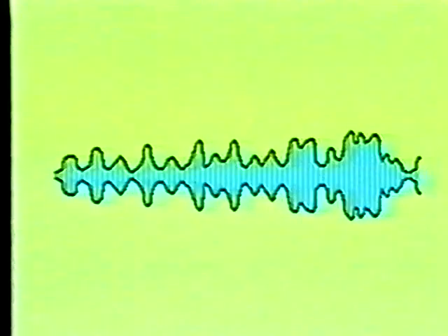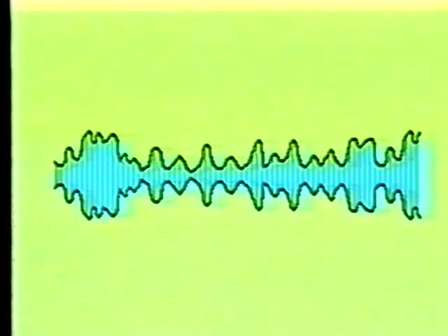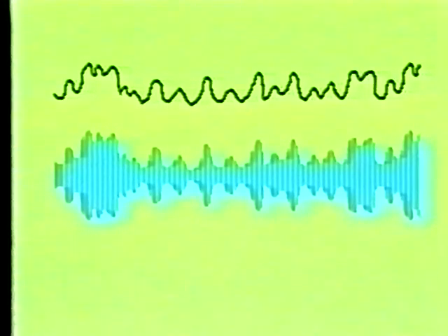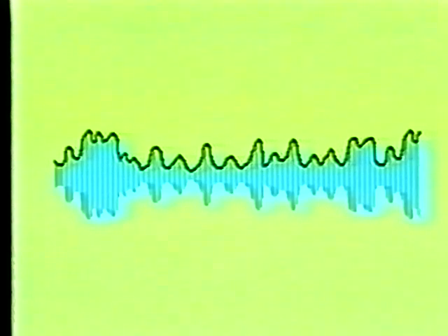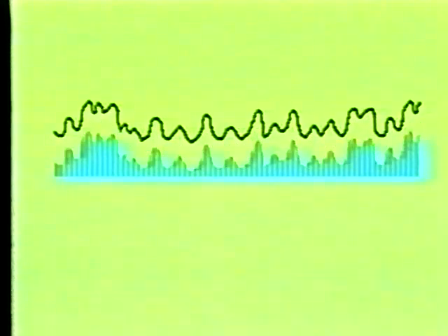As you have seen, the audio signal that was transmitted appeared to be riding on the top and bottom of the RF carrier envelope, whereas in reality, the audio signal was never actually there. Instead, the amplitude of the peaks of the carrier wave were varied so that the audio signal appeared to be riding on the RF energy. Also, since the positive and negative peaks both contained the apparent audio information, only half of the modulated envelope was necessary for demodulation of the input signal.